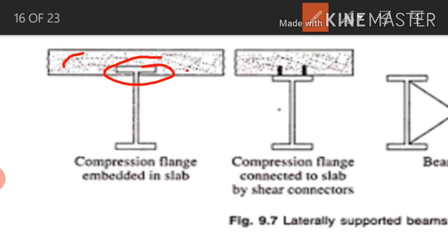If the compression flange is connected to the slab by shear connectors, there also we can prevent lateral buckling.